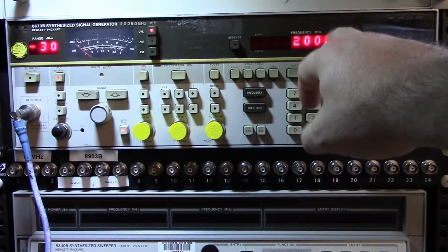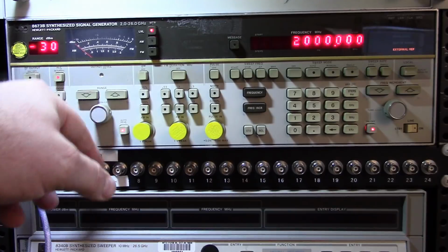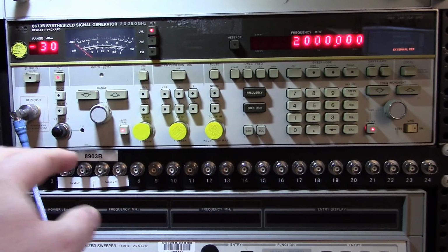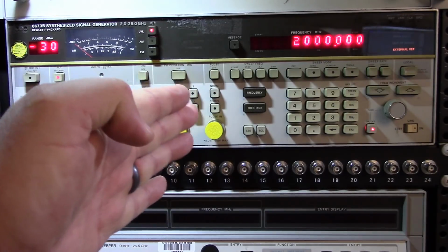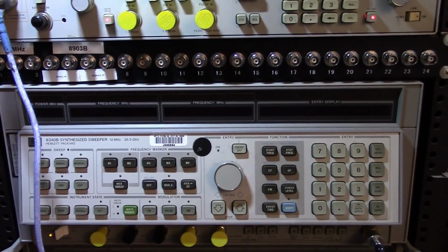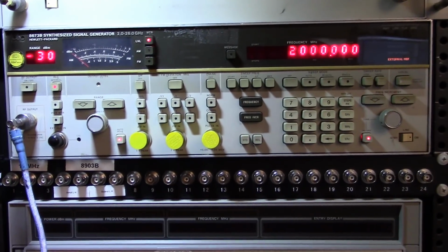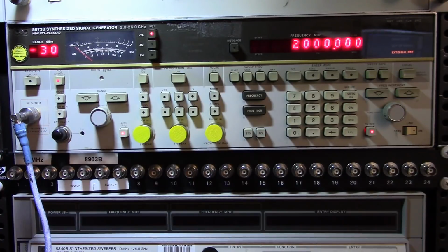So the signal generator I'm using is my 8673B, and I primarily use this as a local oscillator for a microwave converter. But I'm going to use it in this particular case because it has a vernier control on the output, and it enables me to very finely adjust the power. I thought about using my 8340B, which I have here, but unfortunately minus 20 dBm is an attenuator step, so it's very difficult to get the accuracy to get minus 20 dBm.